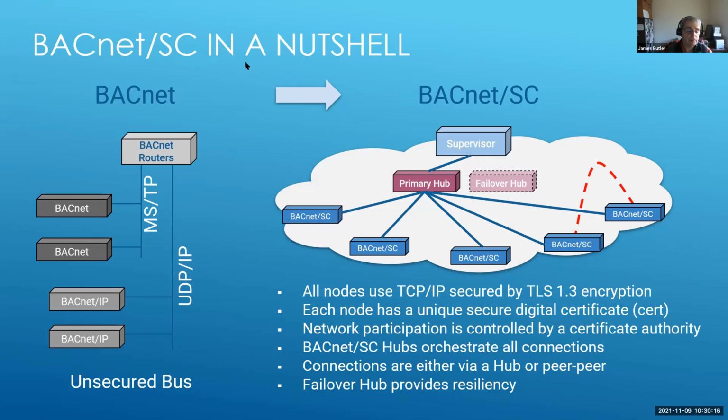And you have larger controllers connected to BACnet IP networks, as well as building automation workstations and servers. And BACnet routers tie these networks together so that you can build larger systems with devices that are optimized in terms of cost and functionality.